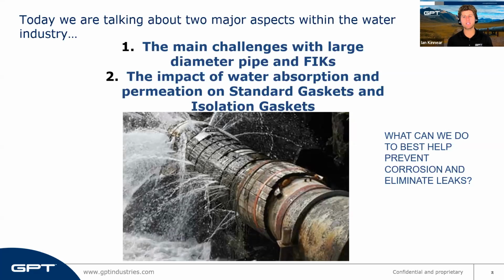Large isolation gaskets play an important role in pipeline protection. And the reason that it has such a focus is because of how extremely costly failure is, right? With these large sizes, there's a lot of installation costs. If you have to deinstall and reinstall, there's the gaskets themselves, the time, the labor, the effort. There's a lot of cost in this regard, and so getting it right the first time is very important.